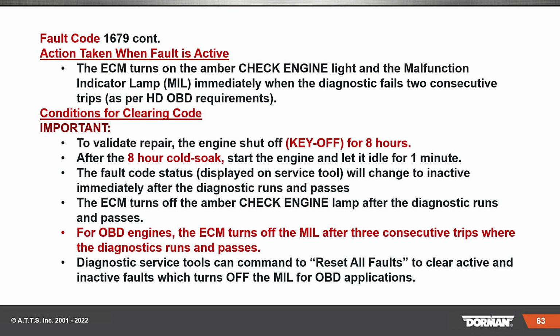Conditions for clearing. Validate the repair, of course. Engine shut off, key off for 8 hours. After the 8-hour cold soak, start the engine, let it idle for 1 minute. The fault code status displayed on the service tool will change to inactive immediately after the diagnostic runs. The ECM turns off the amber check engine lamp, and so on. For OBD engines, the ECM turns off the MIL after 3 consecutive trips where the diagnostic runs and passes.